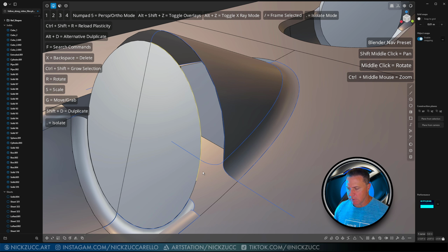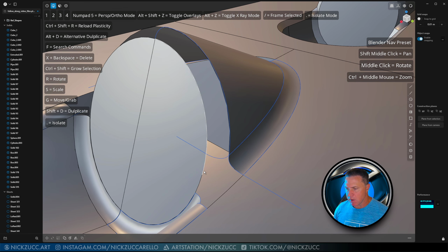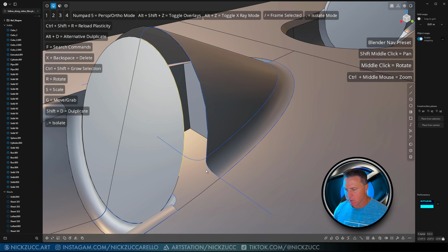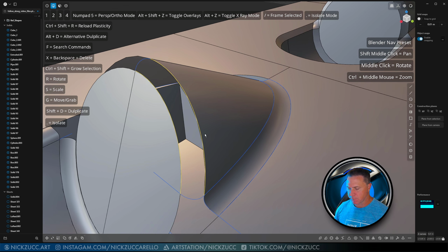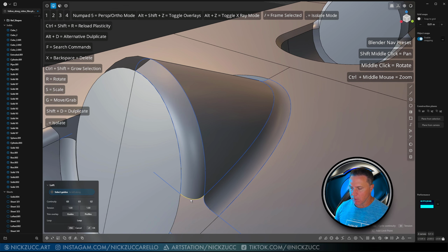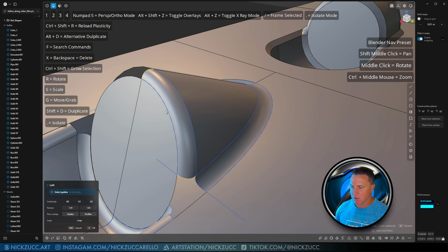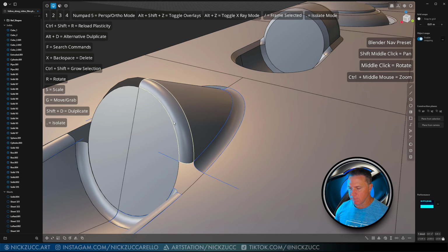And now I can hit 2, and it looks like I might have grabbed the wrong thing on there. So we got this, let's just do this one more time. I'm gonna click here like that, and I'll select 2, hit Alt J to unjoin the curves. There we go. I can get rid of it. All right, so I'm gonna select this curve, tap L, hold down Shift, and you can see we've just built that part for ourselves there.